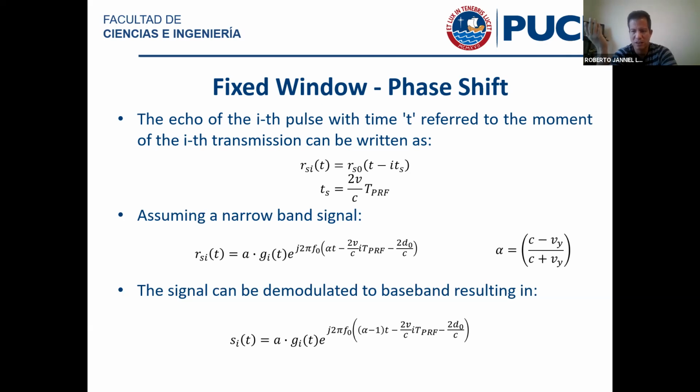Every sinusoidal signal would have to have an initial phase, right? So this is basically saying that you have a signal that has an initial phase, which is given by the last term, that it can also shift if things are moving, and that would be encoded in the second term. And then the first term is just telling you that the frequency itself is going to be shifted if there is movement in the medium, by the Doppler effect. Okay, so again, equations are nice, but the true ability should be to look at them and really digest them and be like, okay, this means this, that means that, and so on and so forth, right?